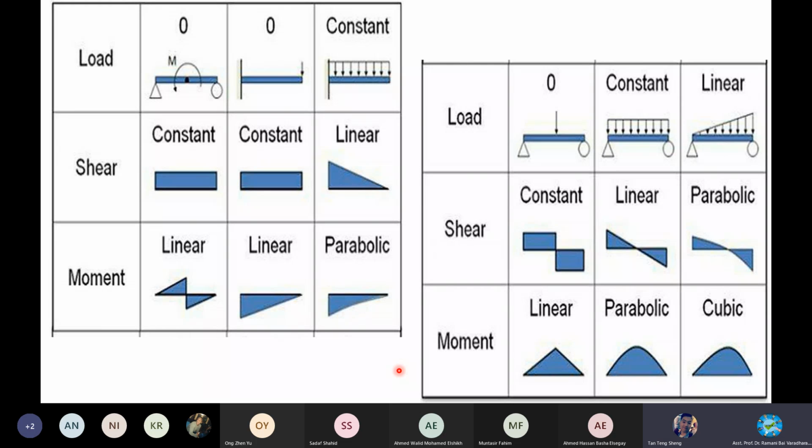By using the area. Very good. Area under the curve will be the value of bending moment because you have force, you have distance. Force into distance can give you the moment. That's why, if not given, maybe they ask some similar question in the exam. Maybe. So if you are asked, if you're not given bending moment, I mean you are given the shear force, if you form the shear force diagram, you can quickly find the bending moment or the maximum bending moment or location of the maximum bending moment by making use of this shear force diagram. We'll do those calculations later, but understand these concepts: where it is maximum, where it is minimum. Shear force and bending moment are reverse.